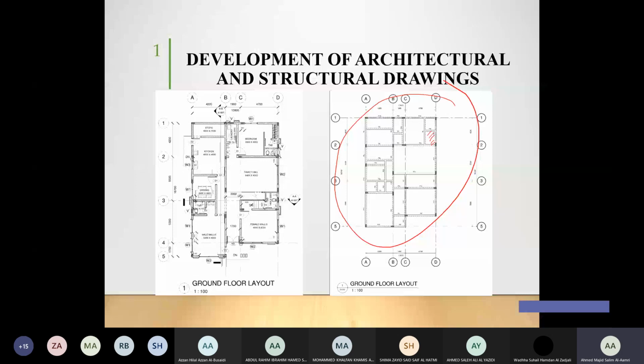The slab does not need to take the load to be transferred to something else, to another element. Directly the slab is transferring the load to the soil. It means we don't need to provide huge reinforcement to resist the bending or deflection happening in the slab. Then, the slab is not going to have huge deflection or big moment, since it's already supported by soil. Are we clear about that?